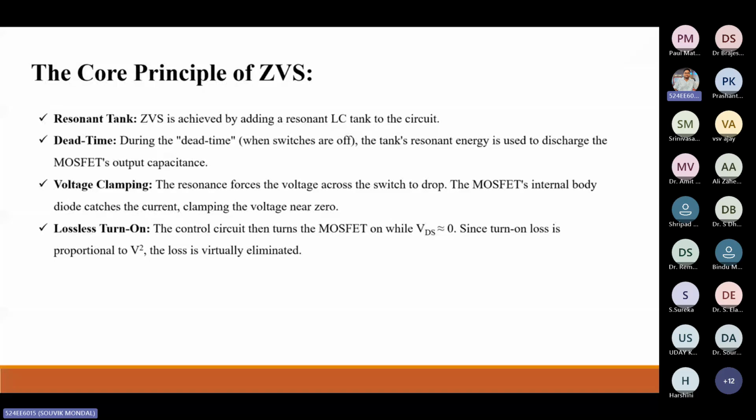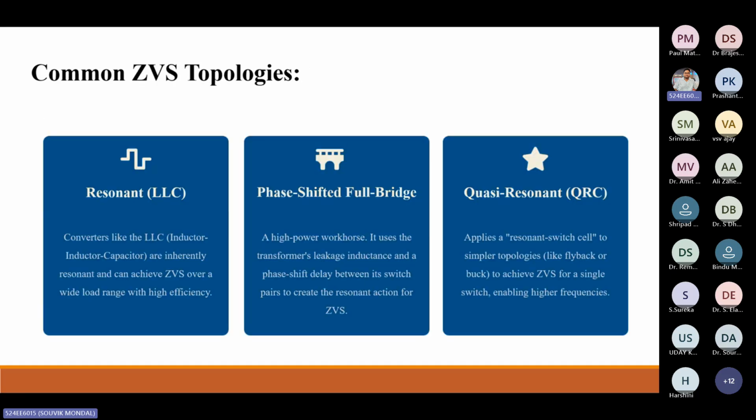In the next slide, you can check that one resonant converter is there. The hardware setup we have not currently done, but we are going for that. The PCB designing we have also done. So commonly the ZVS topologies we are using are this resonant LLC, the phase-shifted full bridge, and also a quasi-resonant circuit.